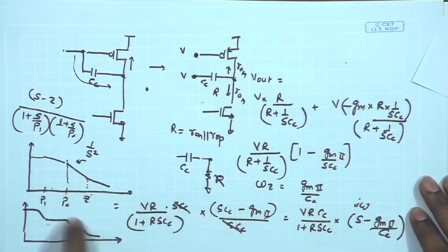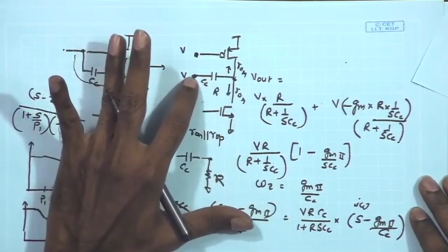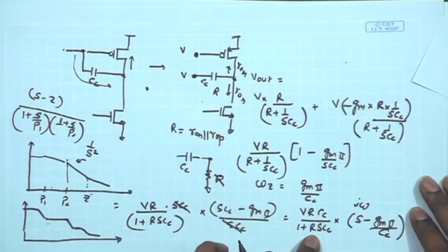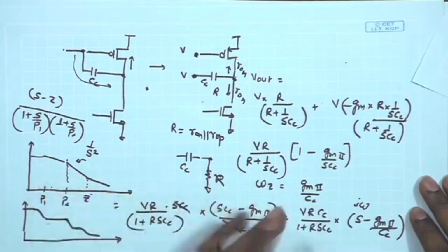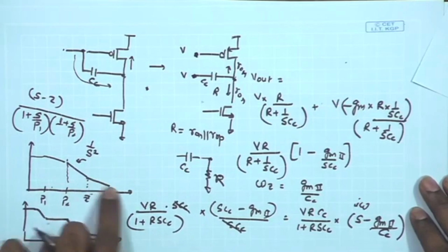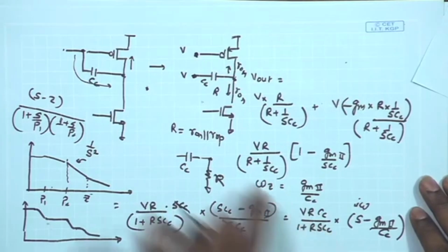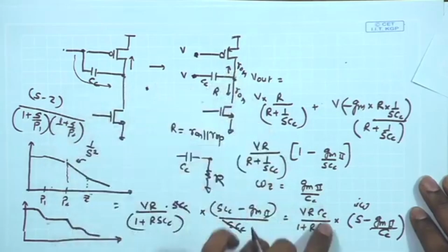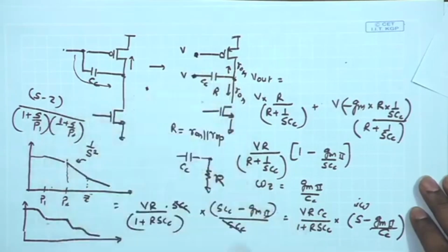So, you have the other poles, so you also have another expression. So, if I look at the R, and if I assume that it comes at a frequency which is much lower than this GM, then you get an overall reduction in slope. And if I compare what is the value of this. So, if you look at R and CC, R is the overall output impedance coming at this point, and CC is the equivalent CC value that you have obtained.